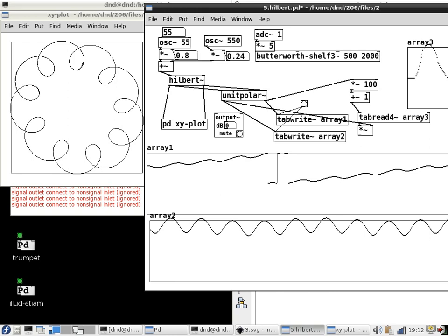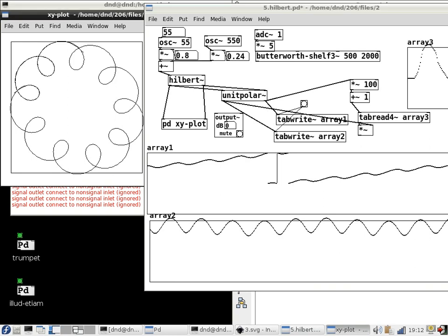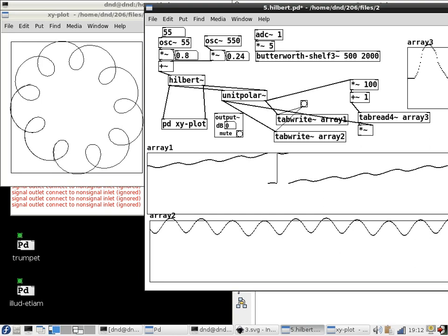Suppose you took, so this is a mess, right? Suppose you just took the x coordinate of this and played it as a signal. What would you get? So that's this. And if you think too hard, or if you think about it at all, it will be hard. But if you don't think about it, it's easy. 2 sinusoids. Why? Because in fact, this is just an all-pass filter of these 2 sinusoids, so you get 55 and 550 hertz exactly.